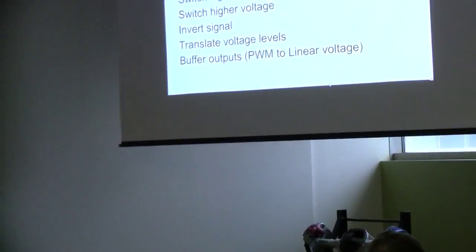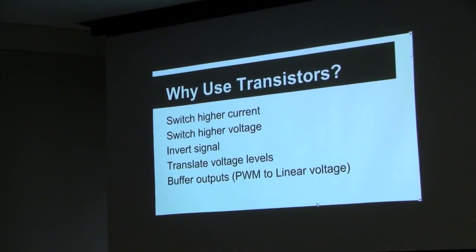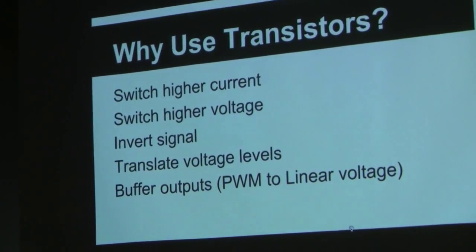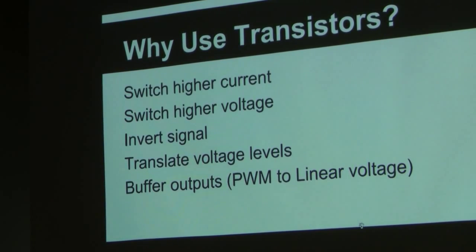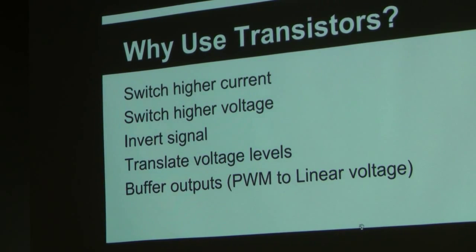Here's Brian's question. Why do I care? That typically we're wanting to add a transistor because we're wanting higher current. Say I'm wanting to switch on a relay that has a 500 milliamp coil or 1 amp coil, or I'm wanting to switch a higher voltage. One of the interesting things, if you're trying to do piezo positioning using piezo crystal actuators, they may need 1,000 volts, but only at a milliamp or 2. There's some MOSFETs that fit that great, that you drive directly from your controller.